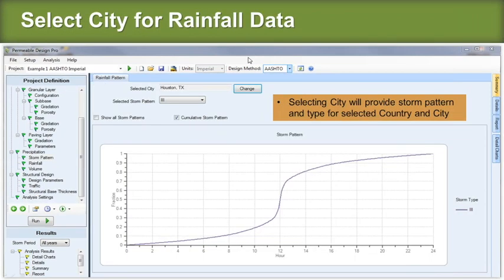Yeah, just to comment on that, please, Dave. Just to comment on the 100 inches per hour. Most permeable pavements when they're new, depending on the joint widths and the jointing stone, are somewhere between 300 and I've seen as high as 800 inches per hour for a brand new installation.